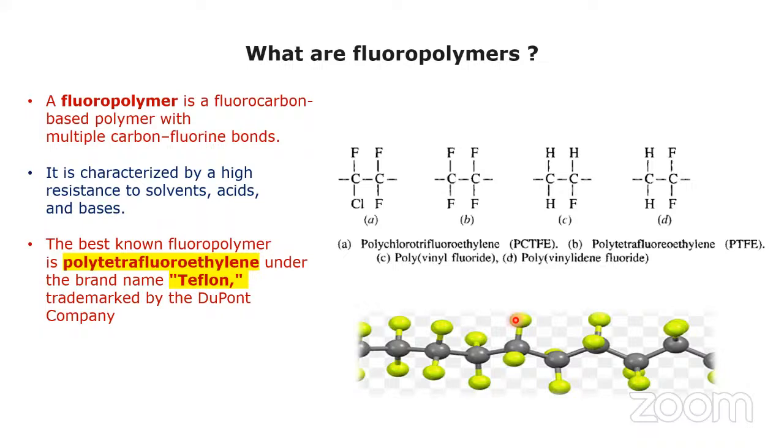For injection molding of PEEK, the temperature goes up to 380 degrees Celsius, minimum 340. Similarly, we have to do injection molding of PTFE as well. It will require higher conditions for injection and extrusion.